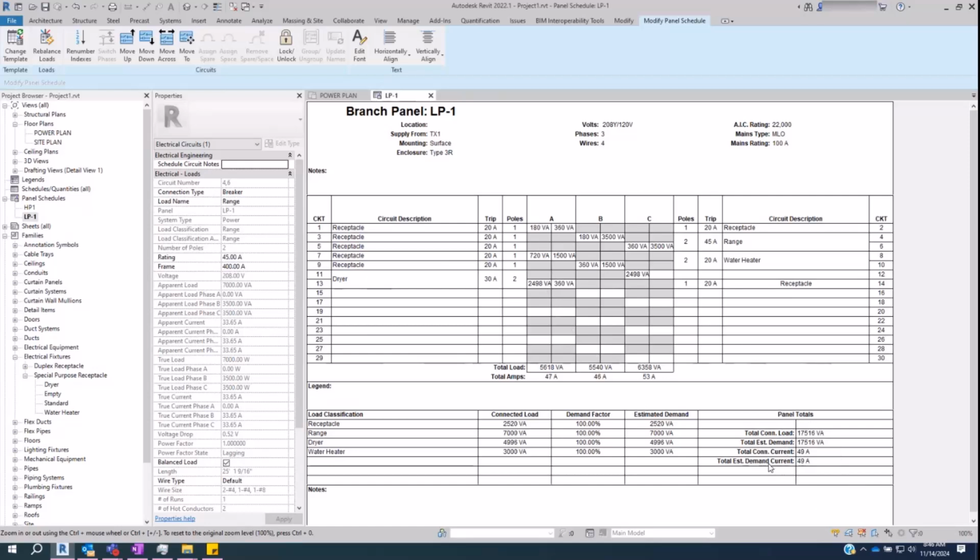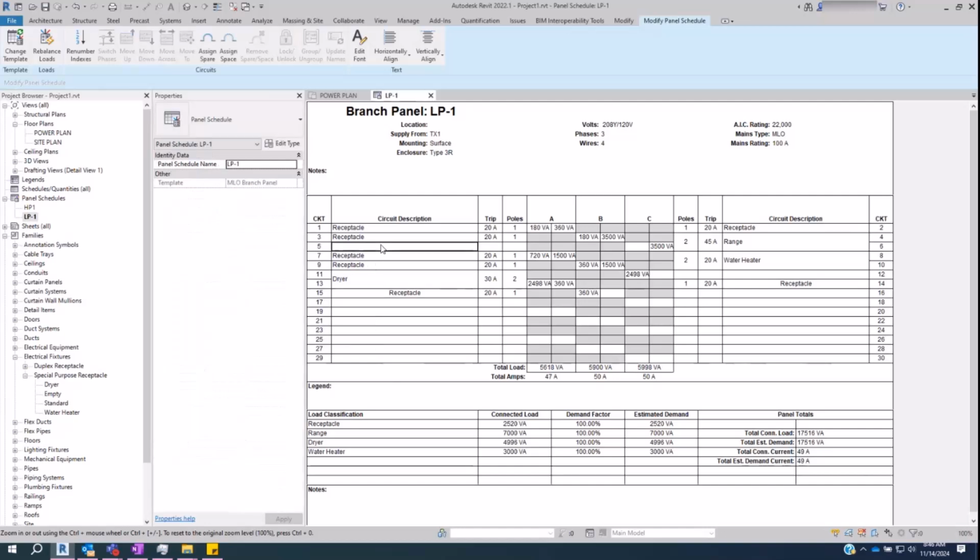So even though we've got a bunch of single phase loads on here. I think if you wanted to make it a little bit better, you can move space number 5 to space number 15. I don't know why you would do that because it's like a random gap, but I think it would make them better. Yeah, you could totally do that. There's no harm in that. So do spare, give them a couple extra spares here, a couple extra spares here, and we'll do spaces all here.